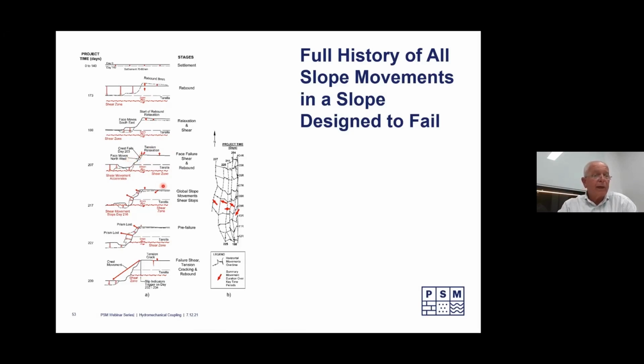We go to the next phase, and we've done a lot more excavation now, and we get a little more shear happening, and this part of the slope wants to go down, and this part of the slope wants to go up. So it's almost a circular type failure. Lastly, just pre-failure, we no longer have any shear. All of the front of the slope wants to fall off.